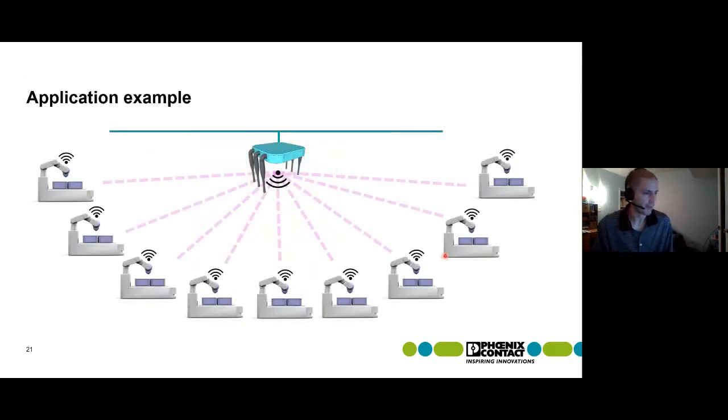Talking about the application on the factory floor, if you have a cell here, an access point with multiple stations or clients, today with Wi-Fi 5 and below, only one of these devices can talk at a time, whether that's access point down to a station or client up to an access point. It's one at a time. These things happen really fast, but if one device needs to talk and another's talking, it has to randomly back off for a random amount of time, and then check the spectrum again to see if it's available. If it's not, it has to wait again.